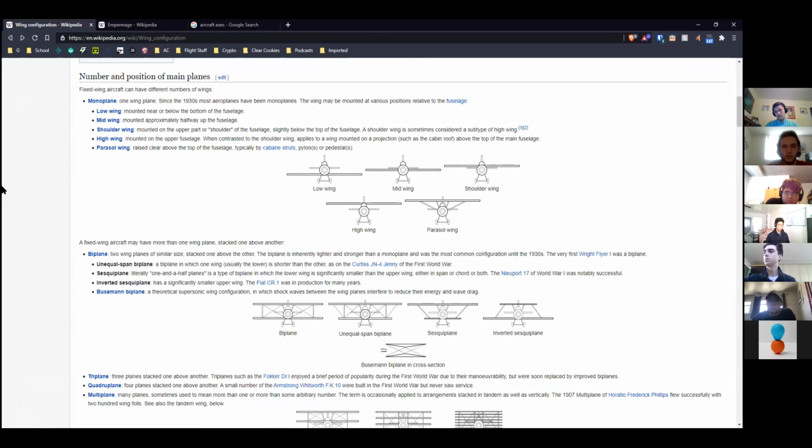You're going to know generally what wing area you want and maybe an aspect ratio after you figure out your performance, but it's still up to you to lay out that area in the best configuration. That's why you need to figure out the shape, and then the position is going to affect your performance more granularly, and it'll affect your controllability as well.